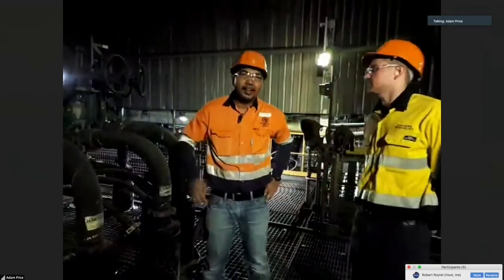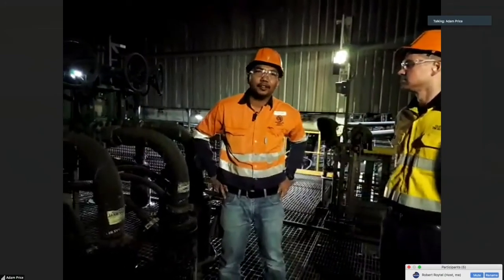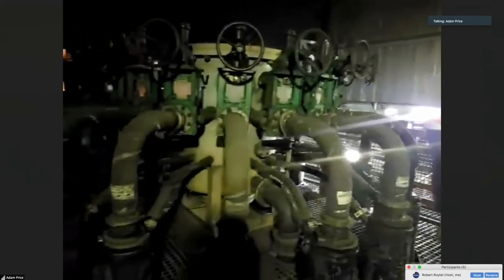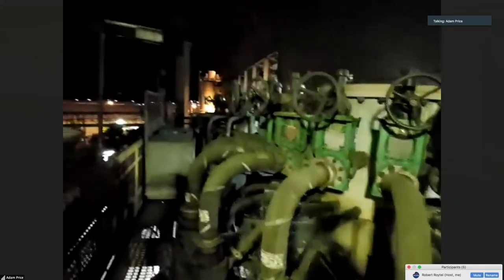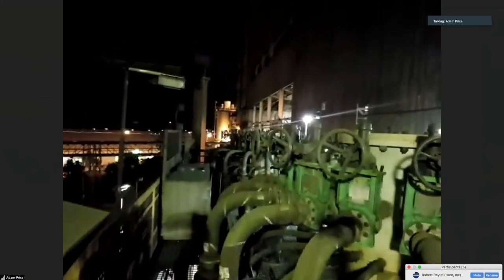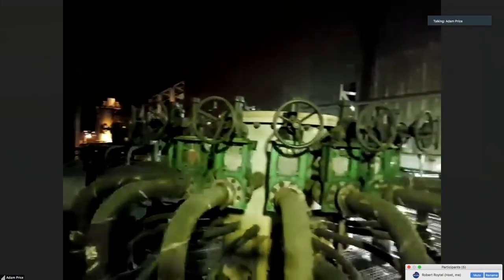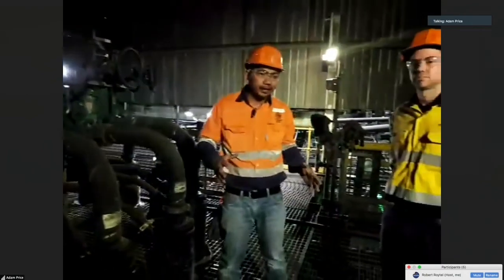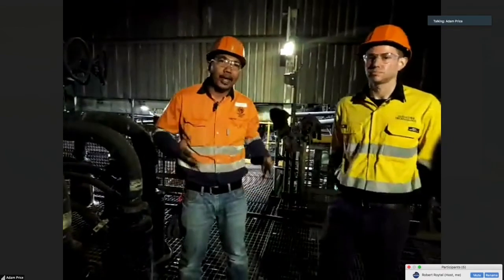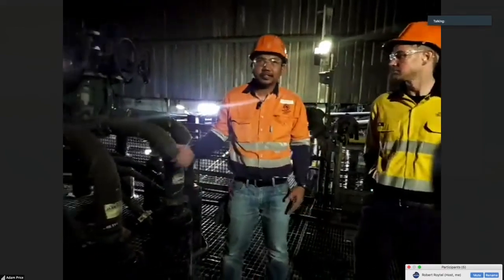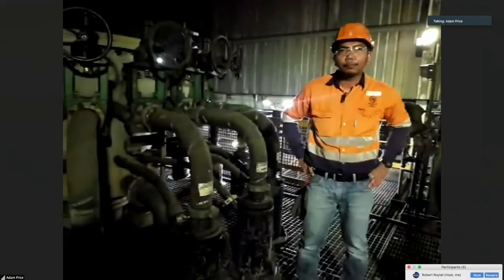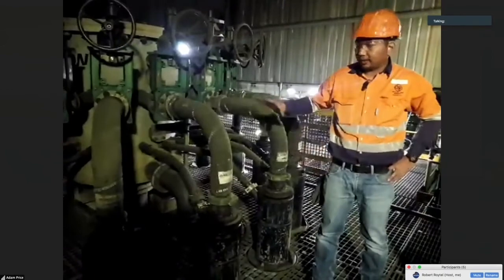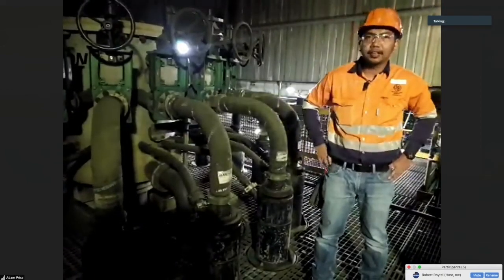Yep. Again, the maintenance aspect is quite a bit easier as compared to the old setup we had. The old setup had 7 agitator banks, which consisted of 112 agitators. So we have to maintain all of those, and in case we have to do repairs on one of the agitators, we have to put the entire bank offline to be able to access it. As compared to the Jameson cells, there's minimal to no moving parts. The only moving part would be the pump, but other than that, we've got the stationary downcomers, and that's pretty much it.